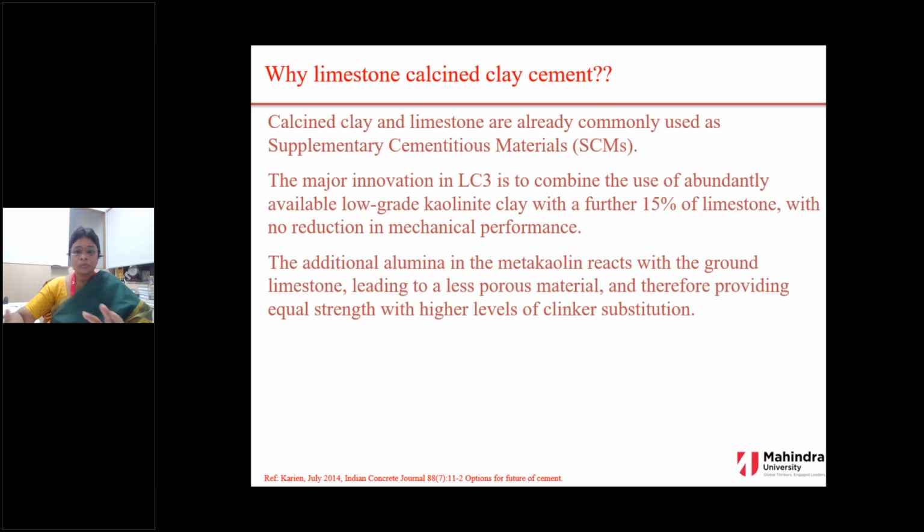So without any reduction in the mechanical performance. In the following slides, I will be comparing the mechanical performance of both concrete systems, but without reducing any mechanical or durability aspects, without compromising on that. If you can achieve higher replacement of clinker, that is the major innovation of LC3.